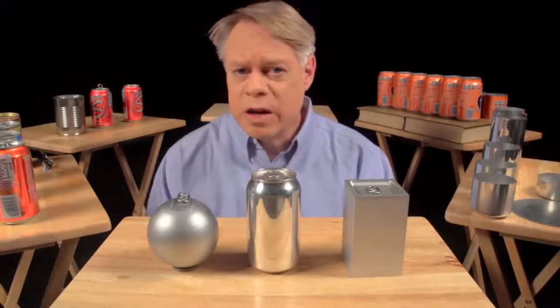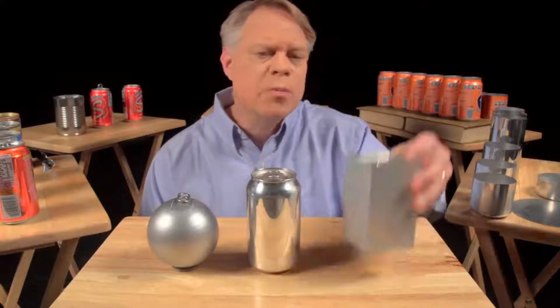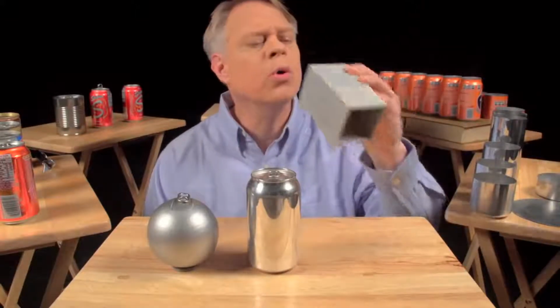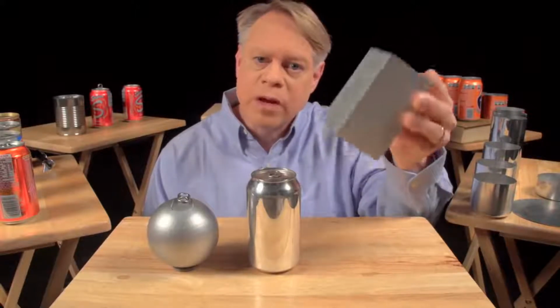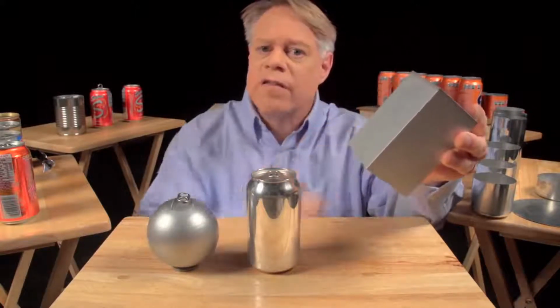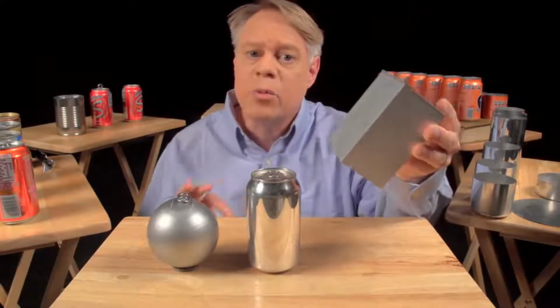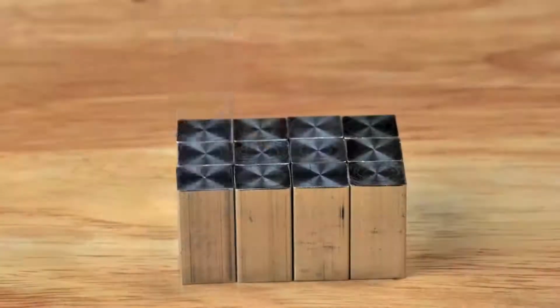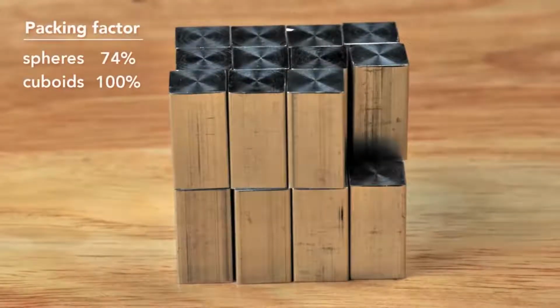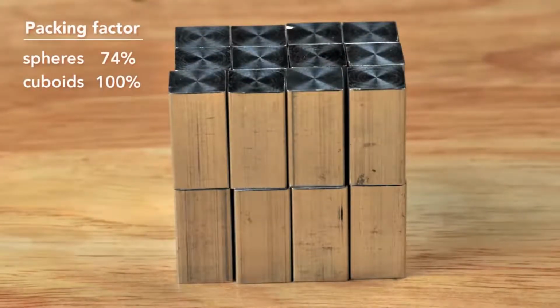An engineer could solve this problem by making a cuboid-shaped can. It sits on a table, but it's uncomfortable to hold and awkward to drink from, and while easier to manufacture than a sphere, these edges are weak points and require very thick walls. But the cuboid surpasses the sphere in packing efficiency. It has almost no wasted space, although at the sacrifice of using more surface area to contain the same volume as the sphere.